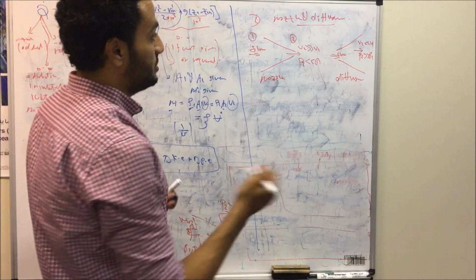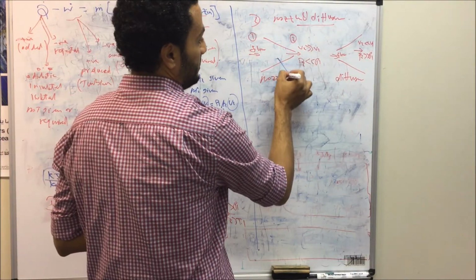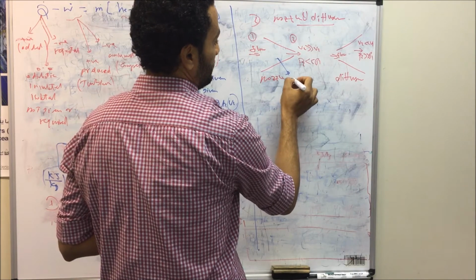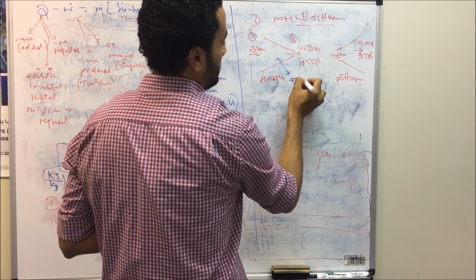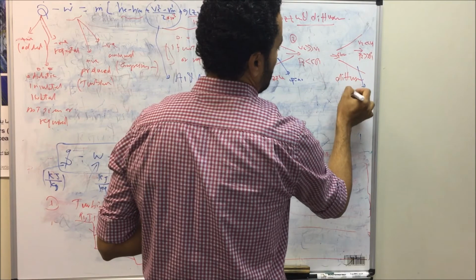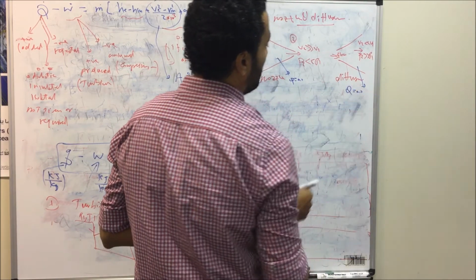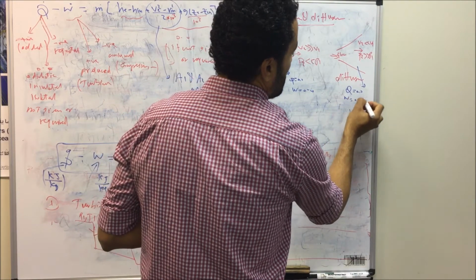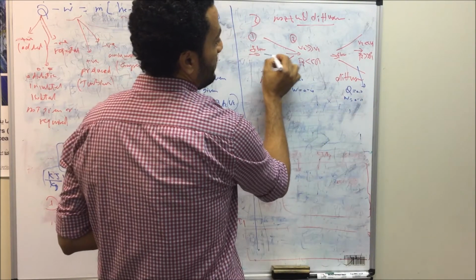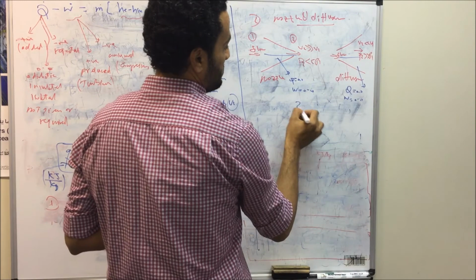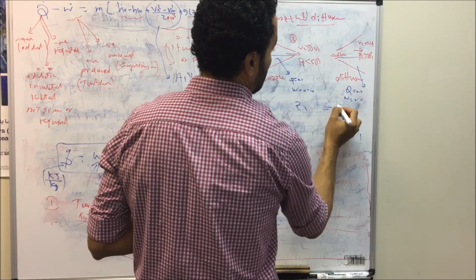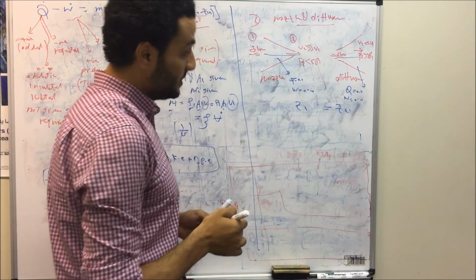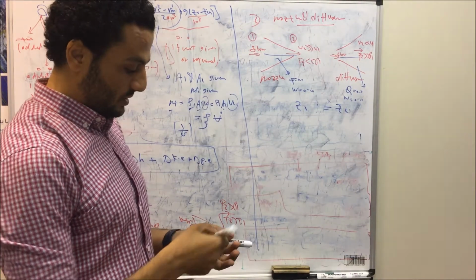Due to the small dimension of the nozzle and diffuser, we consider the heat transfer Q equal to 0. Usually we neglect the heat transfer. And for those systems, the work also is equal to 0. From the inlet to the exit section, we have the same elevation, Z1 is the same as Z2 in most cases, so we don't have a change in potential energy.